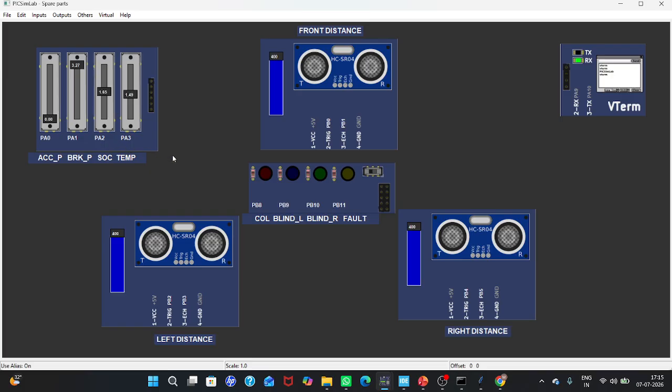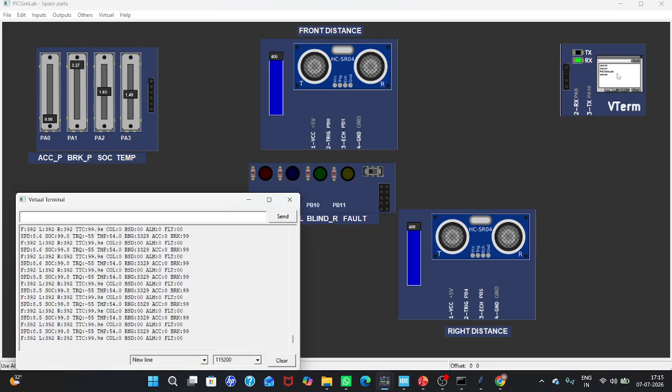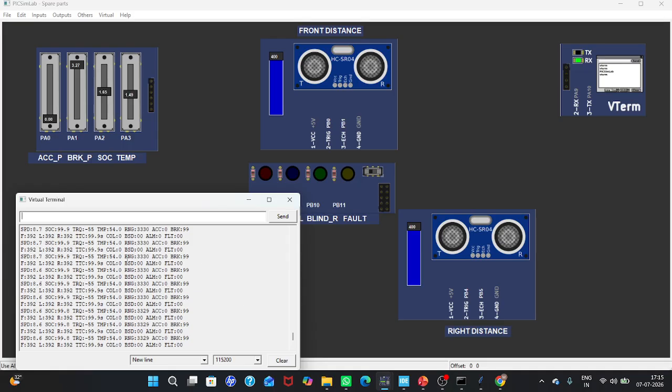The HCSR04 ultrasonic sensor uses separate trigger and echo GPIO pins connected to the STM32. The trigger pin sends a 10 microsecond pulse, while echo pins receive the reflected signal to calculate distance. UART1 uses PA9 as transmitter and PA10 as receiver to communicate with the Python dashboard at 115200 baud.